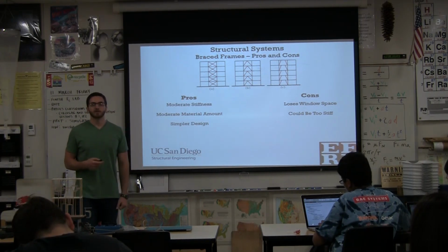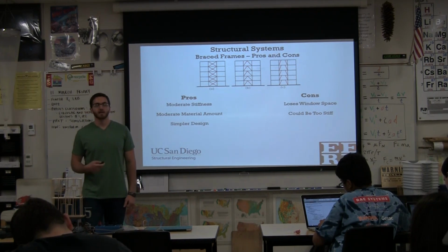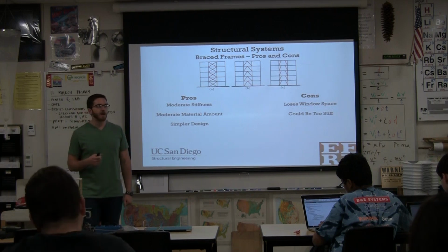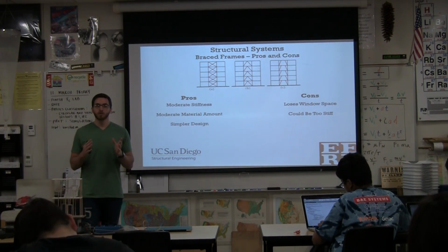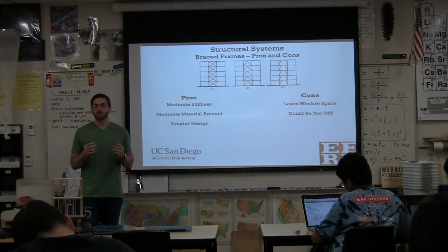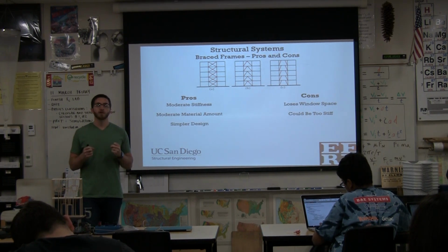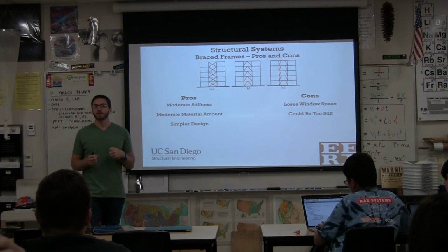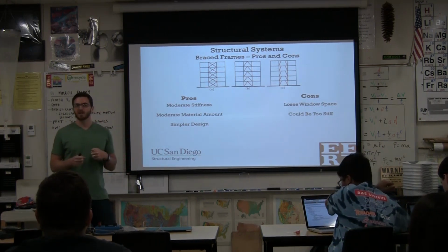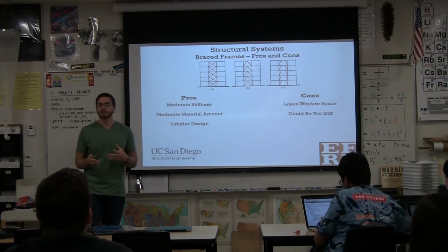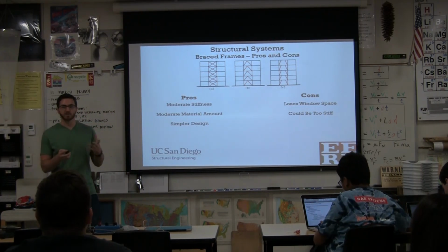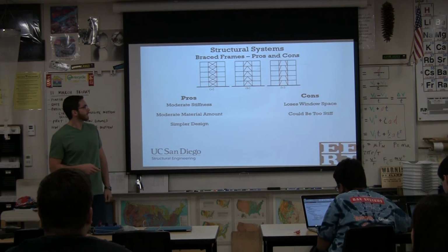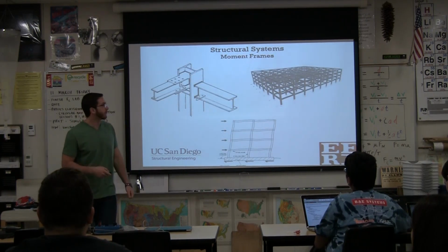The other thing is there's something called ductility. I'm not going to talk about that a lot, but in general, it's the idea that your structure is not supposed to move, but it does need to move a little bit. If it's too stiff, that could be a bad thing. And with braced frames, there's sometimes an issue of ductility. It's sometimes harder to get the exact ductility that you want. Not always. It just takes a little more focused design. Pros and cons here. Okay, moment frames.